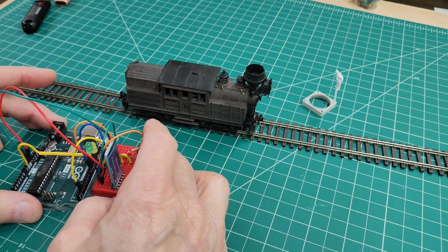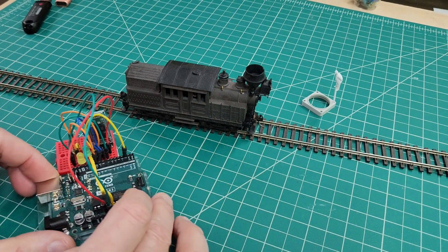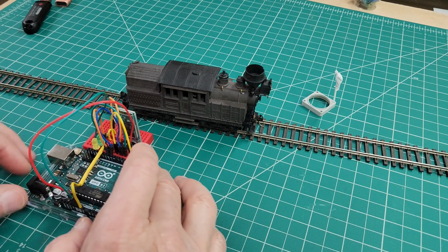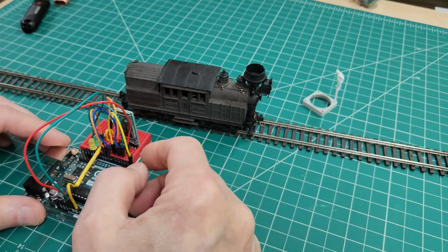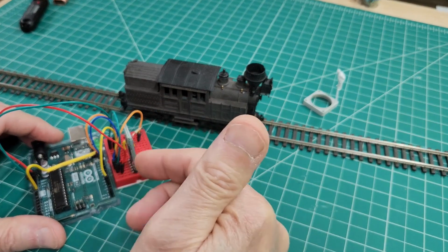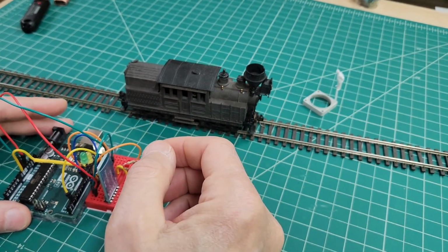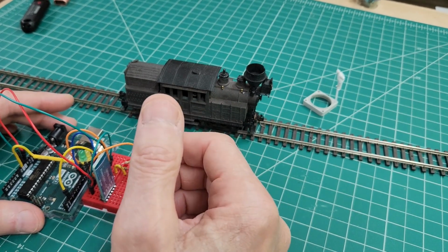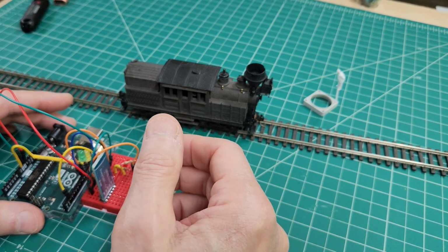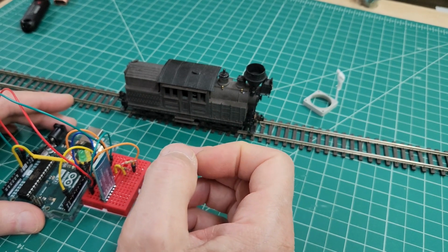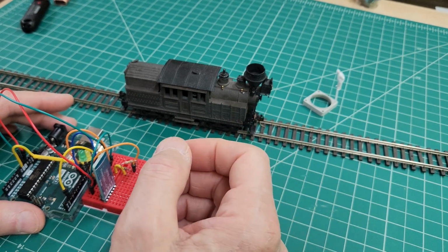As you can see here, there's a couple of LEDs on the board, and I think it was the green one that I was turning on. That trial verified that the wiring to the Bluetooth module was correct, and that I also managed to sort out what Windows did with the Bluetooth signal it detected as the two COM ports.